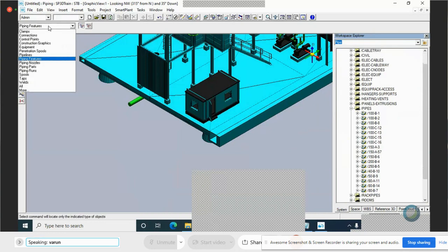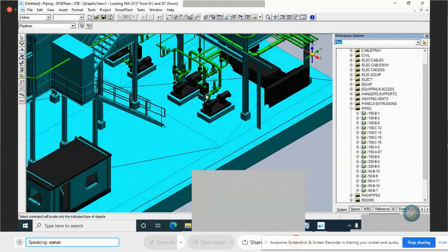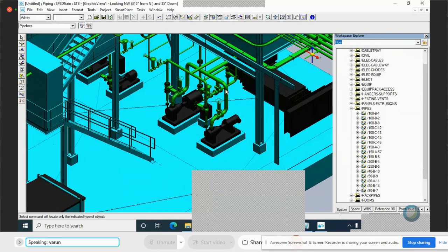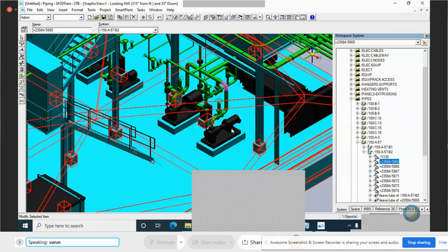So let me show, this is all completely generated from the PDMS. So this is a stabilizer unit from the PDMS. And here, the colors also we can control. And if you see, we can select it as S3D native models, like it's semi-intelligent, where you can select the pipes and objects and see which one it is related to. And basic information, whichever is captured from the PDMS, will be shown. So you can still delete this, wherever you want, you can delete the portion.